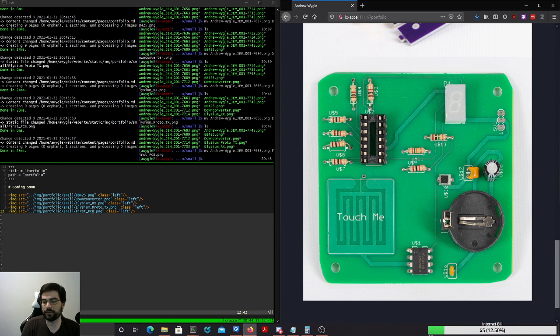Looking at this now, there's a lot of things obviously that are pretty bad. The soldering job on these resistors is terrible. There's like no solder here, tons of solder here, cold joints, all sorts of terrible things. It was also the first time I'd soldered anything. And you can see these ridiculously hair-thin traces for absolutely no reason. It's just nonsense. But this is how you learn. You do things that are not 100% optimal, and then later you do other things that are more optimal.